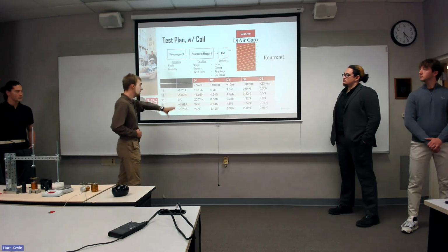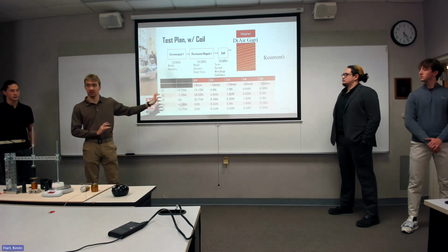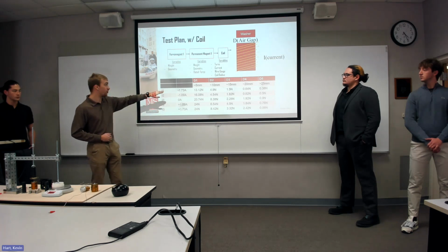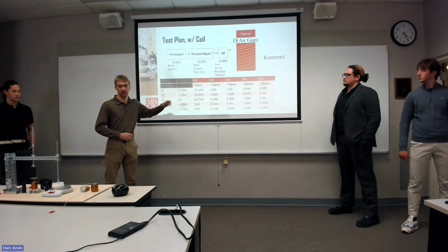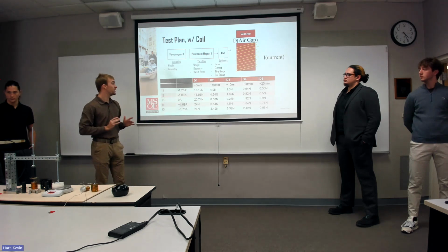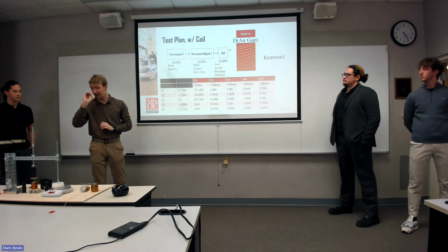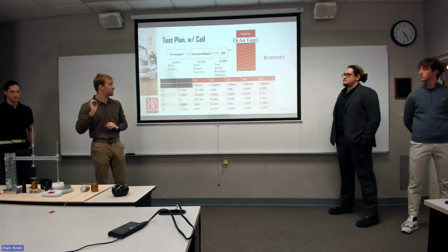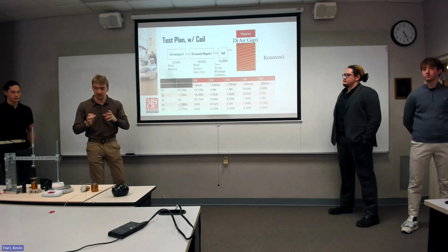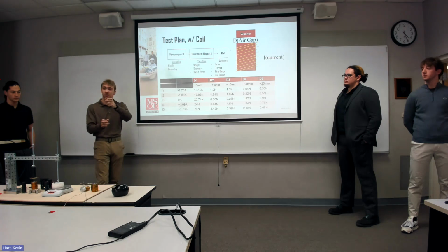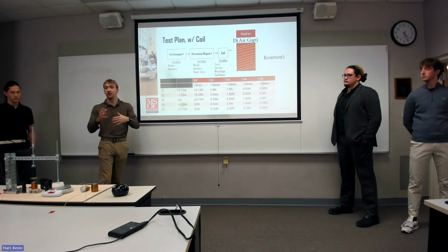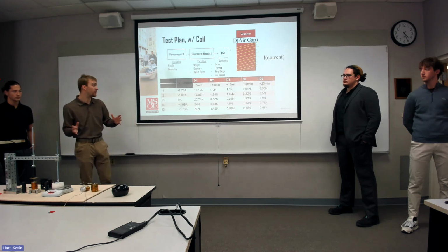In terms of what this table is trying to get at, some of the values are definitely a little dubious. They don't necessarily establish a trend, but that's because these are our nominal distances. So when I was measuring this, especially when you're doing it manually, since the system is so unstable, it's tricky to say, oh yeah, this is exactly 5 millimeters or exactly 10 millimeters. So it might be a little bit higher and a little bit lower. And another thing I noticed is that depending on the orientation of the washer next to the magnet, if you're maybe off center or too close to the center, that will also vary the force a little bit as well, right?